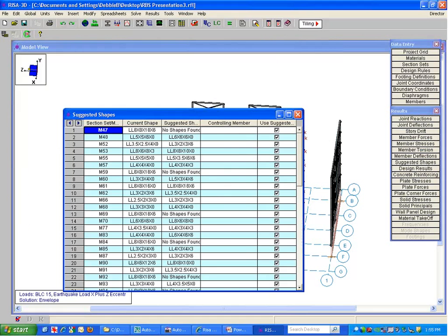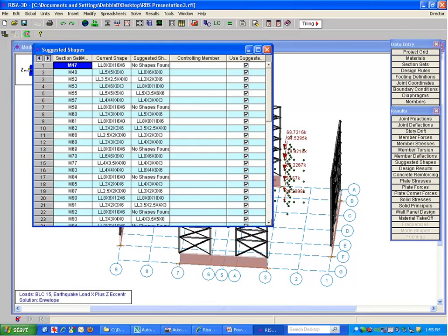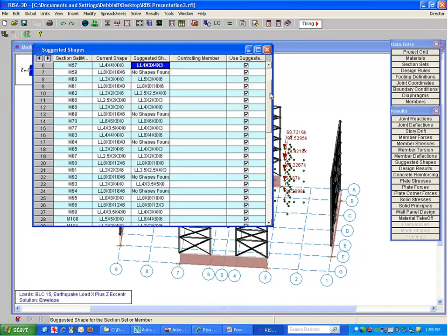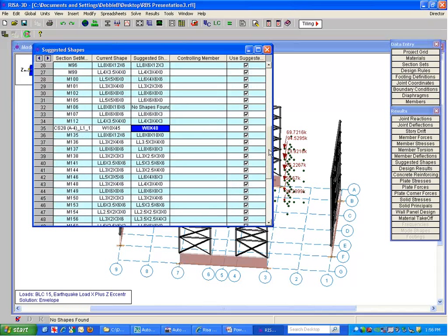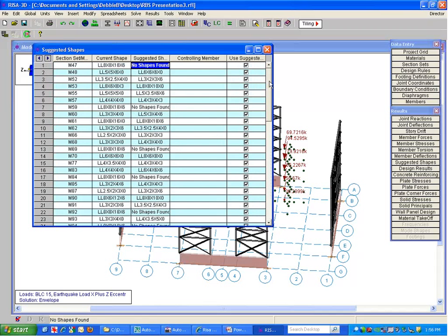And what this does is it looks through the design list and says which shapes would be better suited. So some shapes are just too maxed out. They're not shape bound. But then some are not. Some are actually found for me. So what I'm going to do is I'm going to tell the program to rerun this entire model using every possible shape that it can use to either upsize, or some actually might be downsized. In my model, probably not, okay, because I had so many failing.